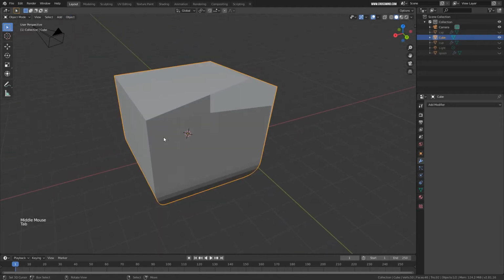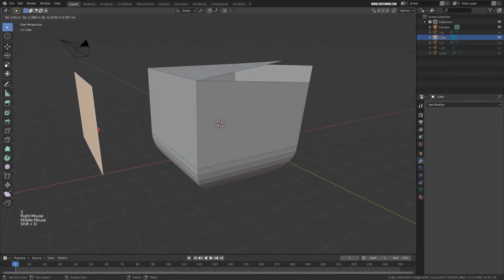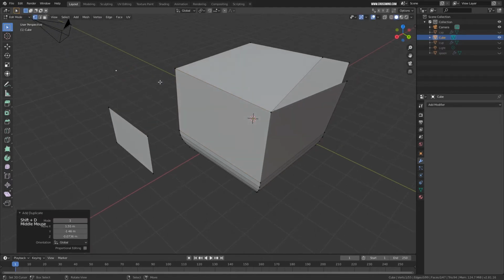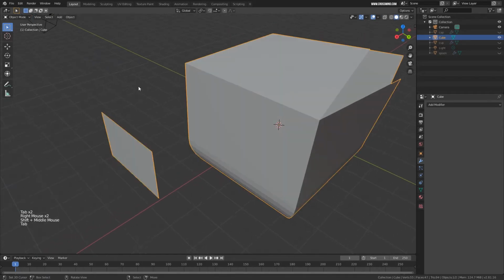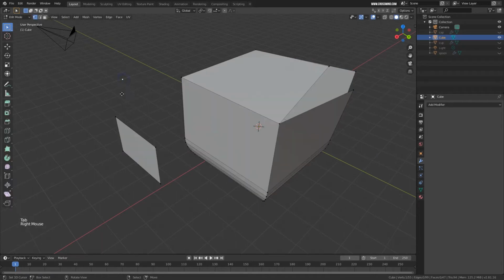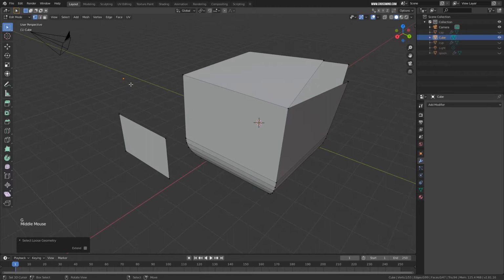Okay, and now let's say if I have this face and I create a duplicate of this, or let's say I have this vertex and I create a duplicate of this. Now this vertex in itself is not going to create any geometry. Okay, you can see this vertex in edit mode, but when you go to object mode, because there is no edge or no polygon, it's a loose geometry, this vertex. Okay, it's bad for any geometry. Sometimes you can see these vertices, sometimes you cannot see these vertices. To quickly clean up your geometry, you can select this one, loose geometry. It's going to select this geometry now, and you can delete it.